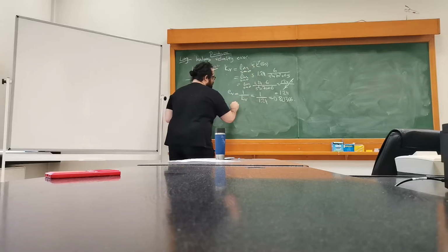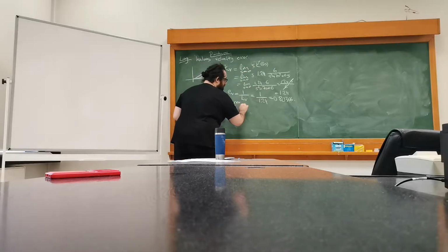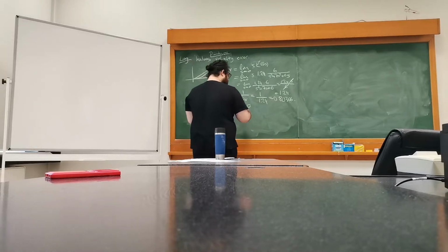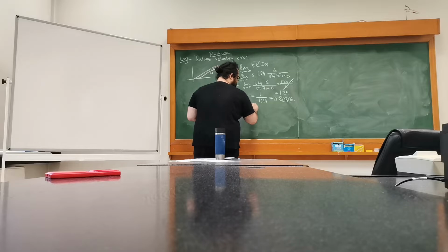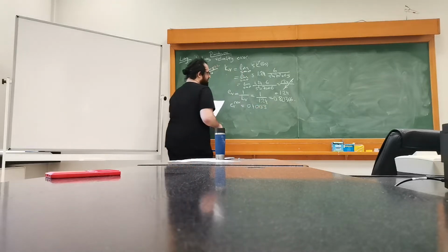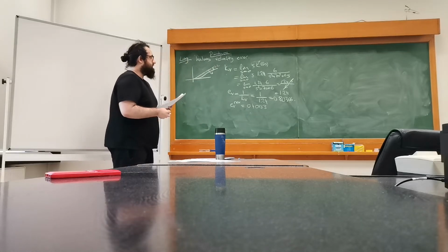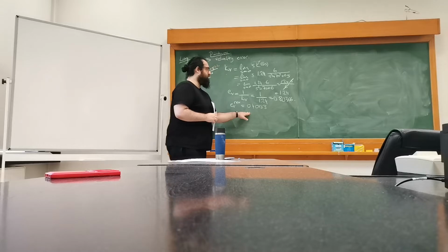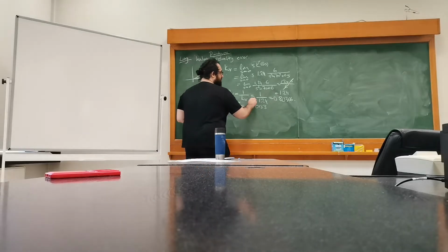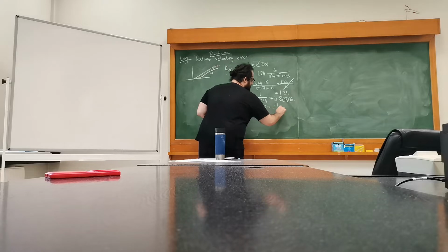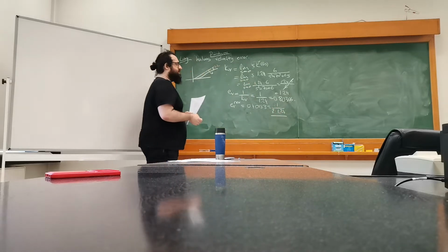So, what we want to really do is add a lag controller in order to come up with a new one, let's call it EV new, that should be equal to 0.4. So half that, 0.40183, something like this. So we want to increase the gain by 2 because this is basically half the error. So in order to do that, I can just see that this would be the same as 2 times 1.24. That's basically it.